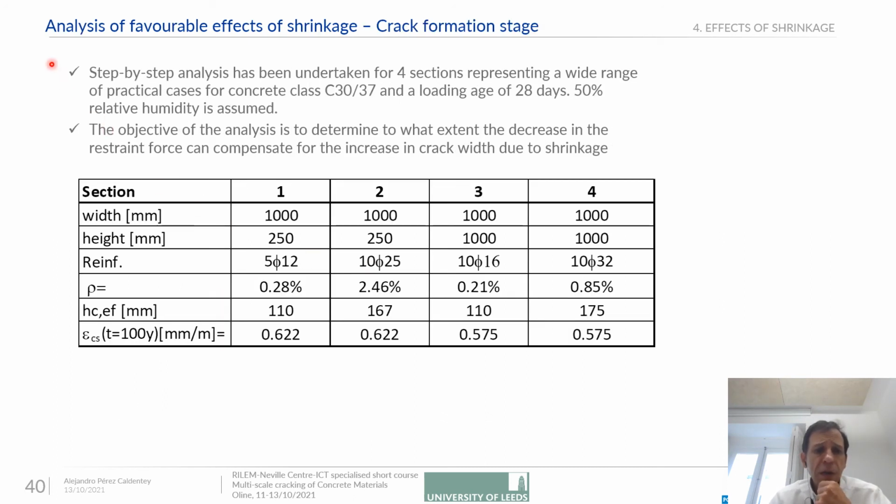So for the first effect, we made a small calculation where we applied step-by-step analysis, to see how the cracking force would evolve through time and obtain from that calculation the crack width. We studied 4 sections which have a very different height and which have very different reinforcement ratios. So you can say they cover pretty much most of the practical field.